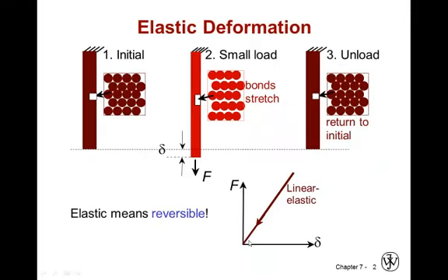Elastic means reversible. It'll just go up and down this particular slope here. Force versus deflection. Put more force on, you get deflection. You take it off, you get zero. Now, some materials will behave in a nonlinear elastic method, but the same concept still applies. You put the load on, and it will deform a certain amount for a certain force, and then you take the load off, and it will come back to its original position.